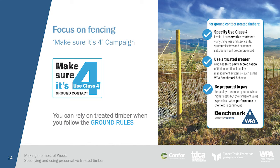With a focus on fence posts and strainers, the strapline "Follow the Ground rules" highlights the basic requirements needed to ensure long-lasting ground contact timbers. Specify use class 4 levels of preservative treatment. Make sure it's 4. Use a trusted treater who has third-party accreditation. Be prepared to pay for quality. And let's look at each one of those in a little bit more detail.